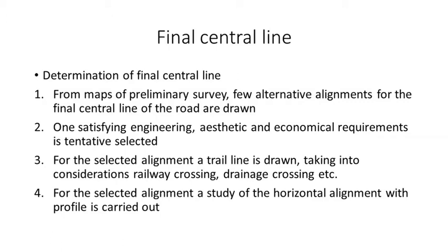So the main objective of the preliminary survey is what? Nothing but fixing the alignment proposed in the reconnaissance, and collecting all the necessary physical information. Okay, so that means in the preliminary survey we have to find out the physical information and details of that topography, whether it may be drainage or it may be soil. So after the reconnaissance we require to collect all necessary physical information and details of topography, drainage and soil, and that can be carried out in the preliminary survey.